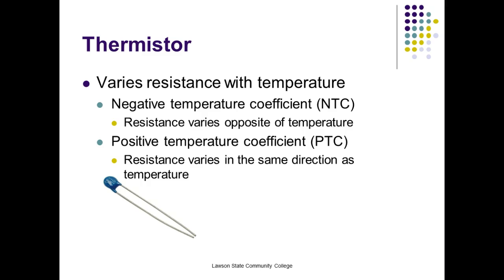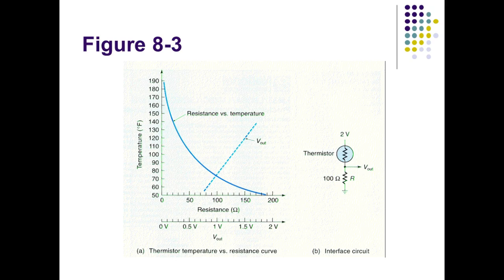So that's pretty much what there is, though, is that they're not linear. A PTC has basically a different curve. These are the ones that are used most often, so these are the ones that we'll look at on the test. So it's non-linear, but the problem is, if I'm in my house, it is going to run on a very narrow band, and that's pretty dang linear within that very narrow band, right? You understand? But thermistors are not extremely accurate, but they're accurate enough.